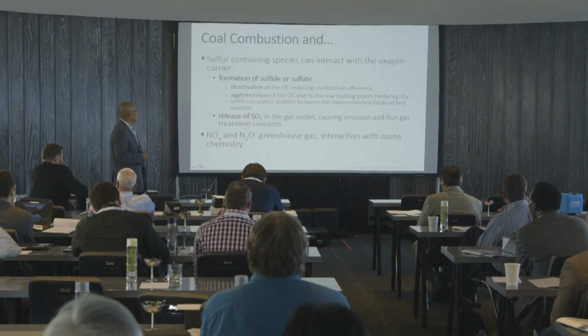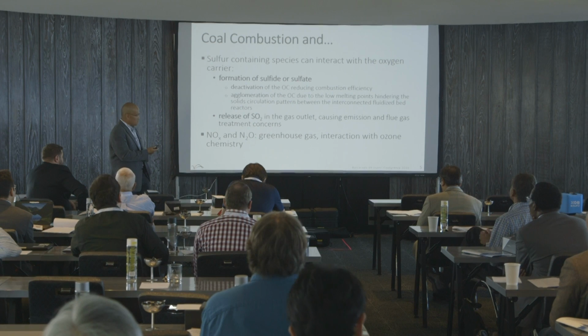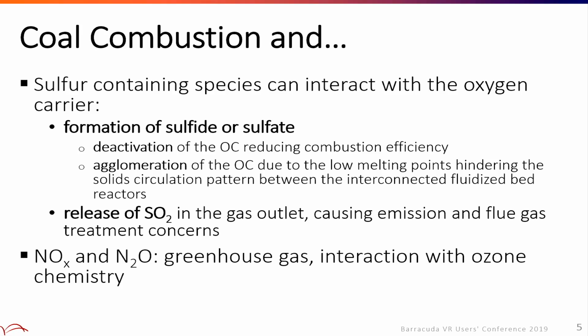Also, because we have another entity here, the oxygen carrier, that can react, for example, sulfur-containing species can interact with the oxygen carrier by forming a sulfide or sulfate, which can deactivate the efficiency of the oxygen carrier. Also, agglomeration can happen and change the circulation pattern in the system. SO2 release from the sulfur is also an emission concern. Coal also has nitrogen, so NOx is obviously a concern as well.